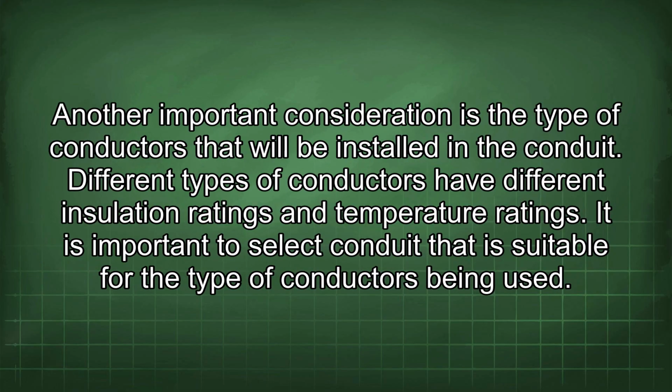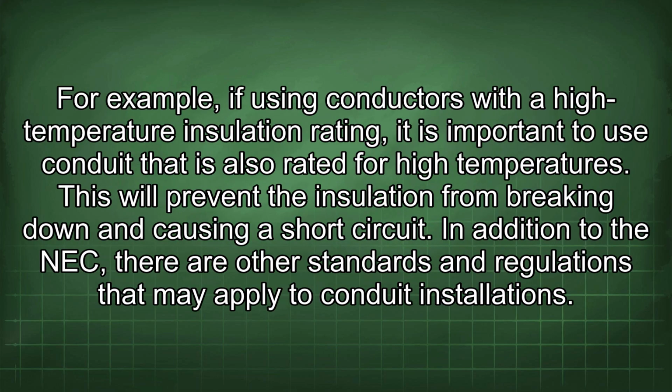Another important consideration is the type of conductors that will be installed in the conduit. Different types of conductors have different insulation ratings and temperature ratings. It is important to select conduit that is suitable for the type of conductors being used. For example, if using conductors with a high temperature insulation rating, it is important to use conduit that is also rated for high temperatures. This will prevent the insulation from breaking down and causing a short circuit.